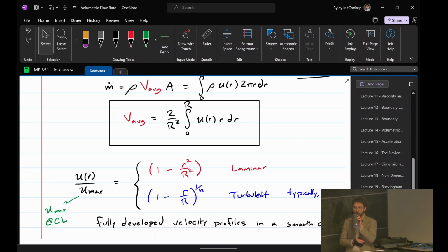Turbulent flow just looks faster than laminar flow. Is it more efficient too? Efficient is kind of a... the drag is different in turbulent and laminar flows. I will say though, the overwhelming majority of engineering applications have turbulent internal flow. It's just a fact of life because the flow rate required is high enough that you have to have internal turbulent flow. Any other questions?